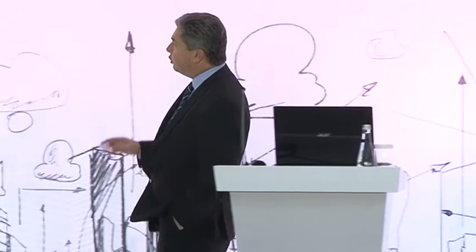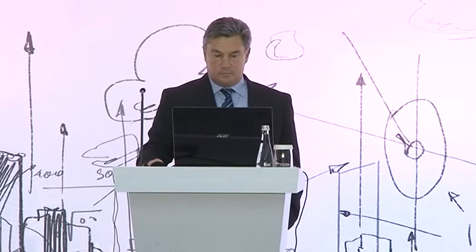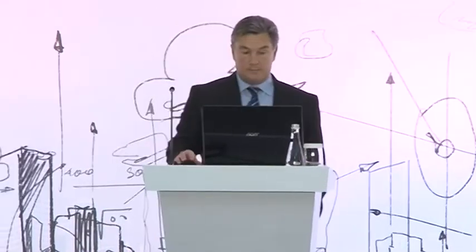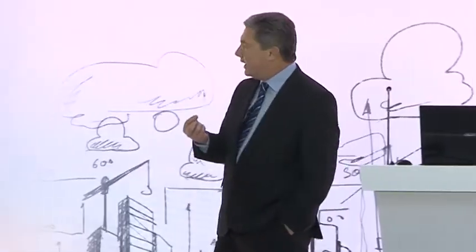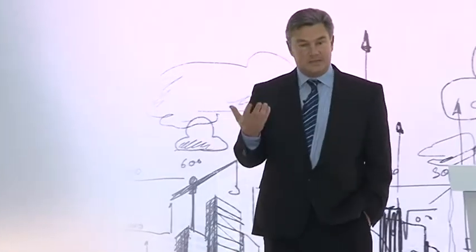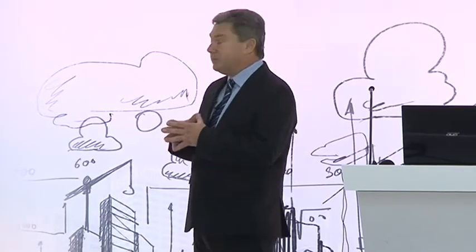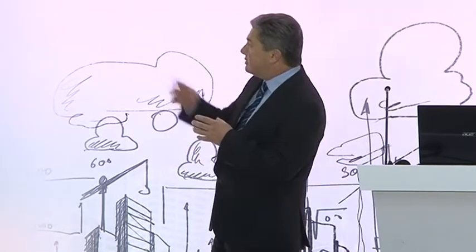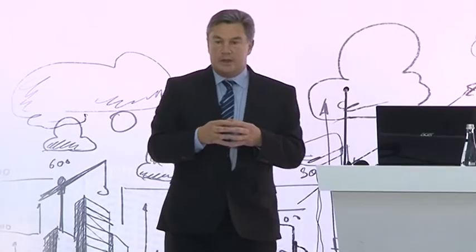Okay, so there's some more options up here. We can turn off the progress summary, if you like, up the top there. And we can apply weightings as well. That's quite important. If you're doing a cost-loaded or resource-loaded curve, that's easy to do because a more expensive activity is going to impact the curve more. But if you're doing a duration-based one, it treats every activity as the same. So you can apply weightings inside of Primavera or Microsoft Project, etc., to say this activity is more important than the other, and it will.